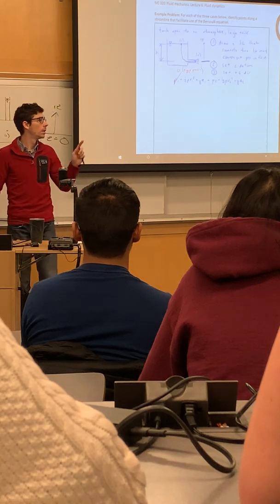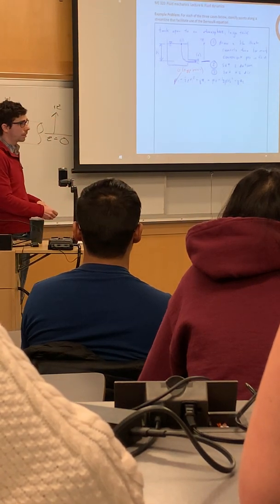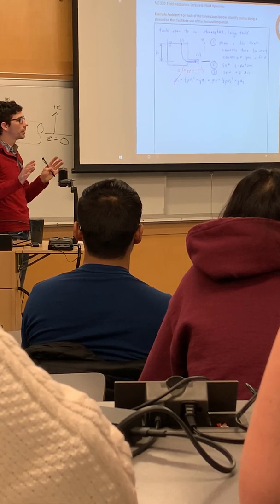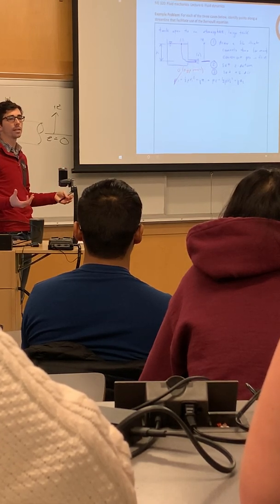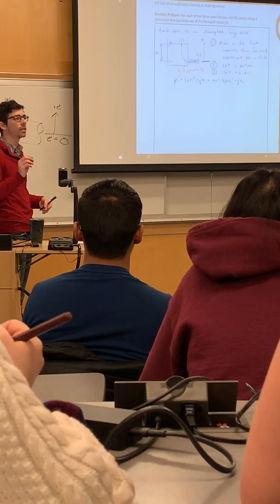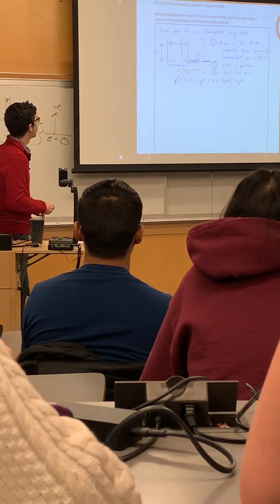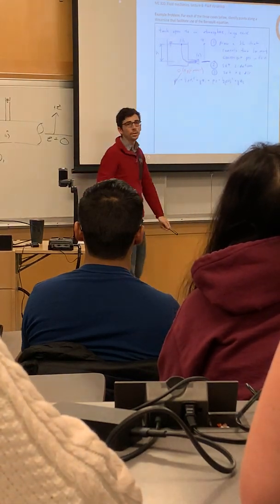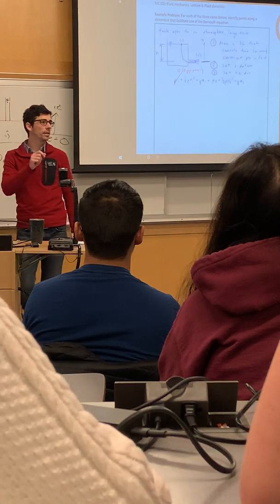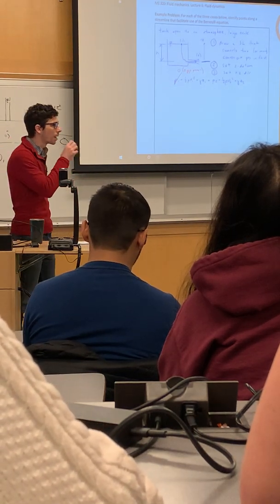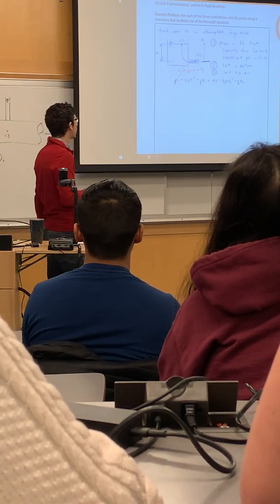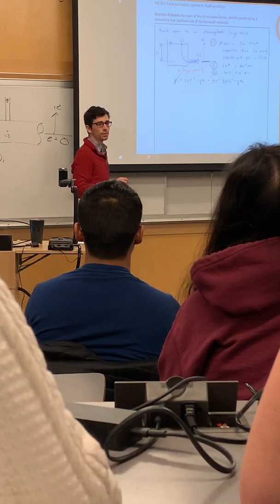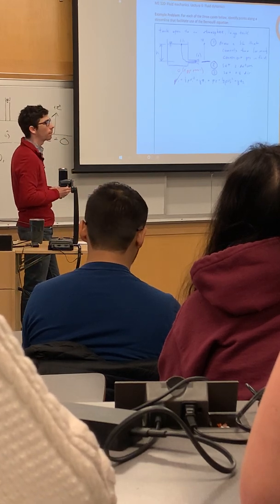So the velocity at point 1 is 0. That doesn't mean the velocity at point 2 is 0, and you have to realize that this is a simplifying assumption. It is not literally, explicitly physically true, right? Even for the largest lake and the smallest flow, you could be really nitpicky and calculate how much your water bottle is dropping the elevation of that lake, right? But for the purposes of math, it's in the noise, right? That's what we're assuming with these types of problems.